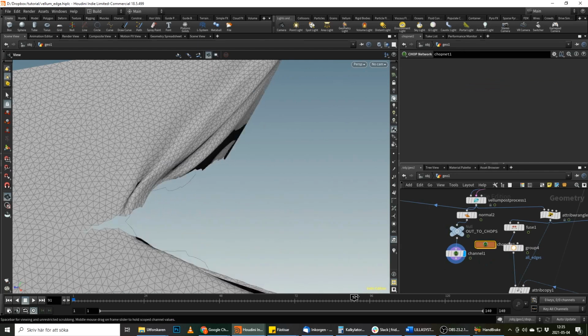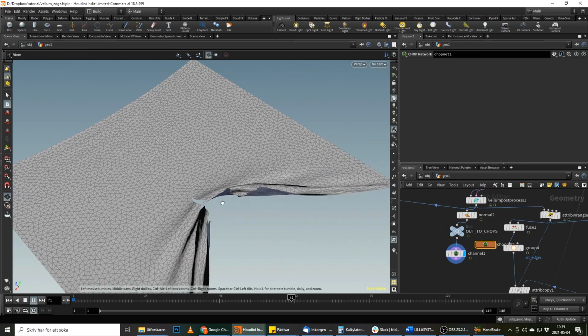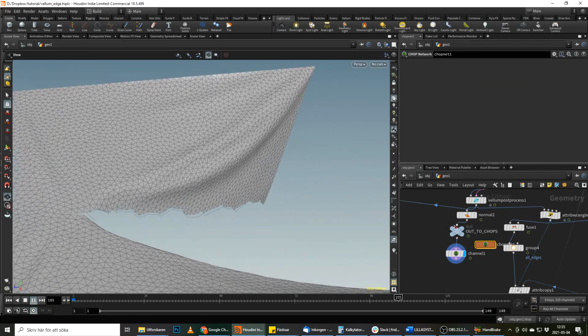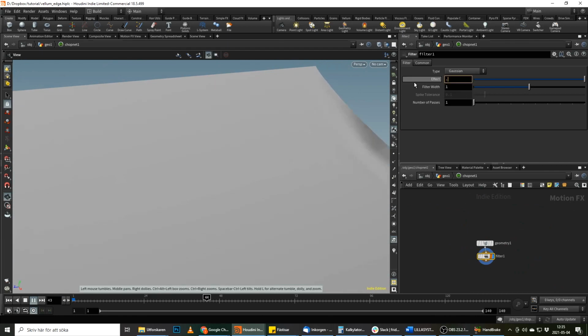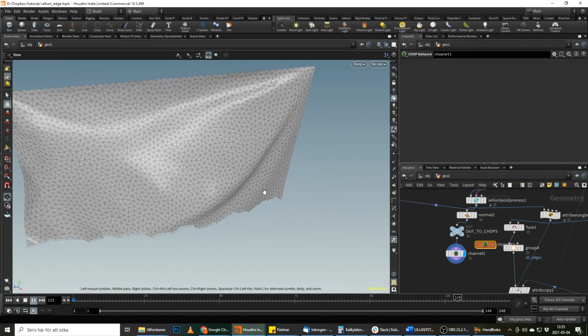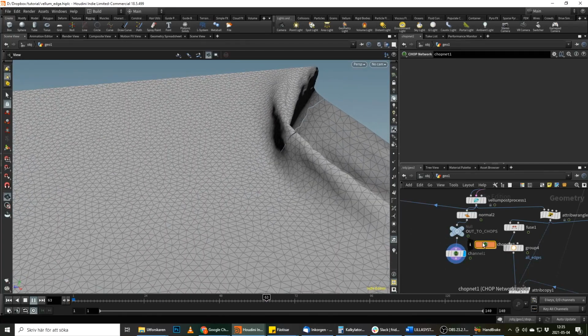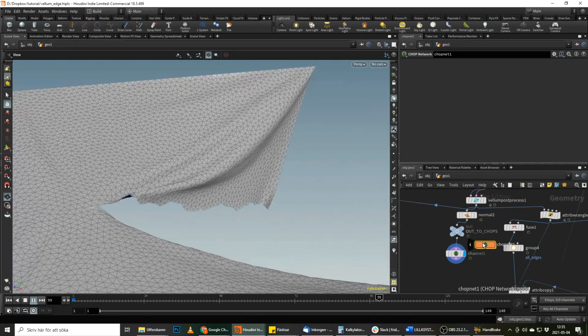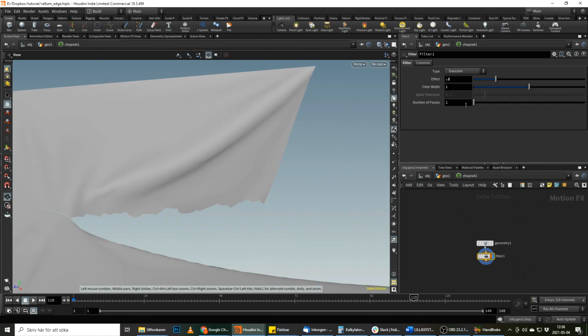We get a lot smoother. It looks like underwater almost now. You see it's super smooth, which might be something you want, but you could also bring down the effect to maybe 0.2 or something, and you get a little bit smoother result if you want that. So that's also an option, and you could also bring down the filter width to maybe 0.5.